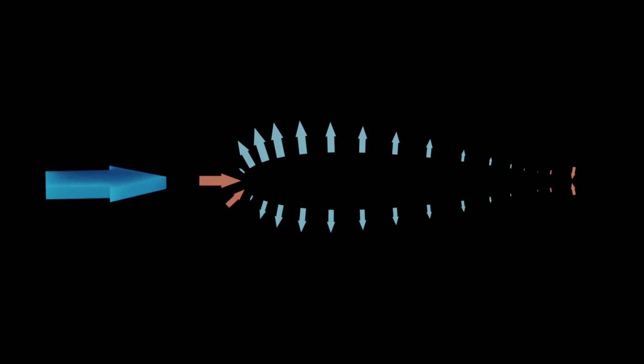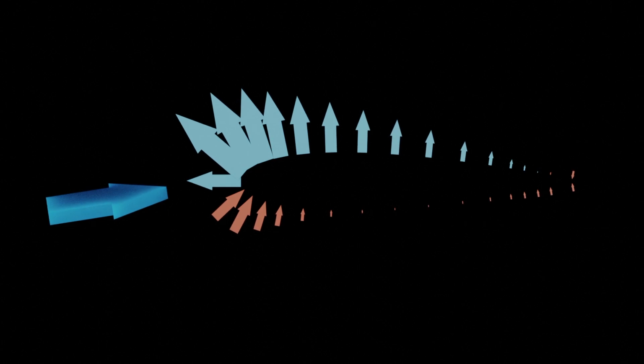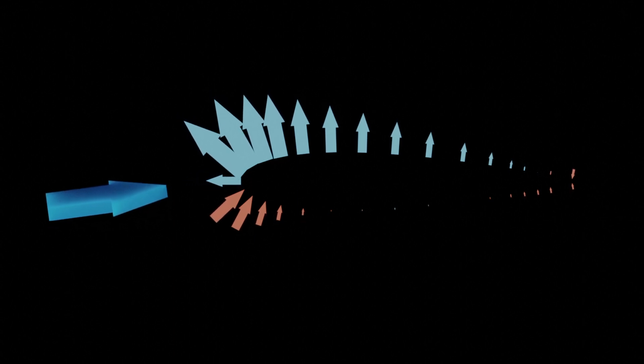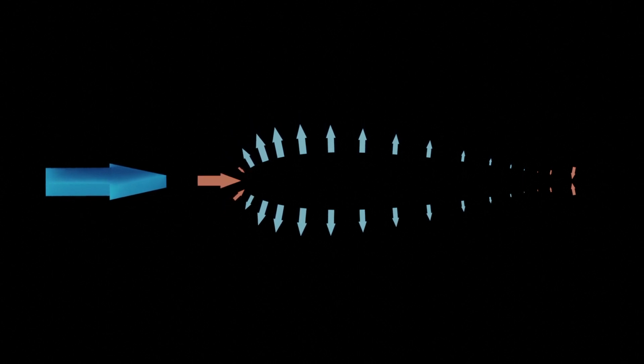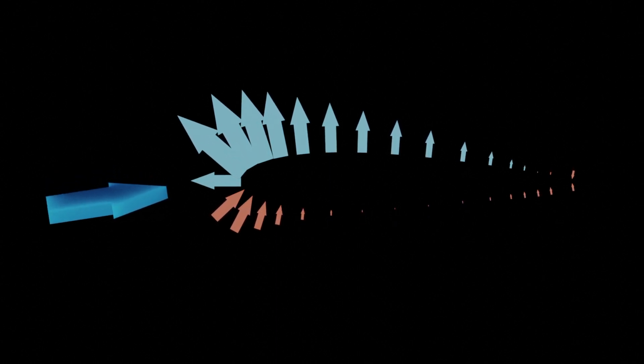This is perhaps easier to understand if we plot the pressure as arrows on the surface of the foil. The length of the arrows will be proportional to the pressure, and the direction and color will indicate whether it is positive or negative. We'll use red for positive and blue for negative. At 0 degrees, the pressures are equal on both sides, cancelling any resulting force. The boat then tends to remain on course. As the angle of the flow changes from 0 to 10 degrees, the pressure distribution changes dramatically.